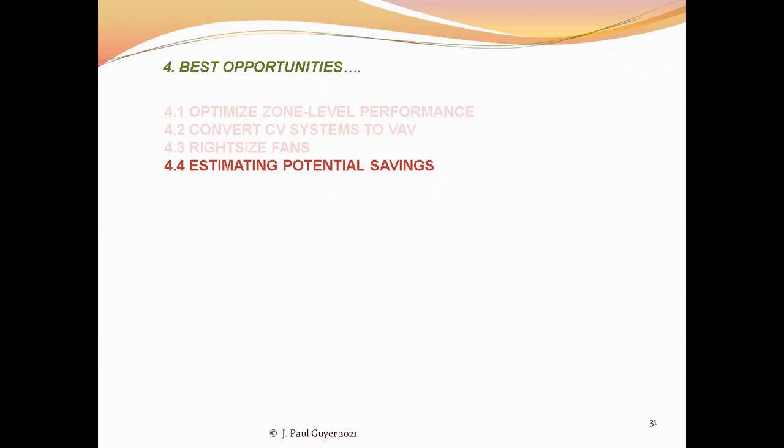Some premium efficiency motors operate at slightly higher speeds than the motors they replace. And because a fan's power consumption increases in proportion to the cube of its speed, it's important to compare the nameplate speed of the existing motor with its premium efficiency replacement.